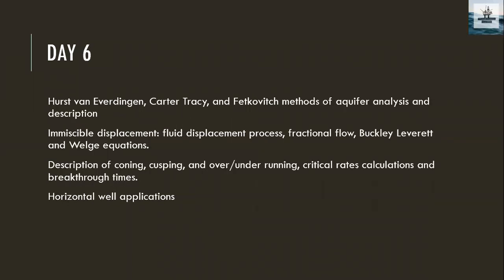Then comes aquifer estimation. The amount of water that gets encroached into the reservoir will be understood by different scientific formulas: first the van Everdingen, Carter-Tracy, and Fetkovich methods of aquifer analysis and description. These scientists have given numerical formulas for the amount of water encroaching into the reservoir, which we are going to use in Excel to estimate with the help of other parameters.